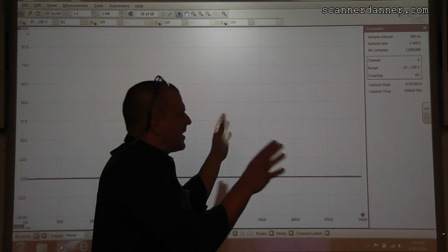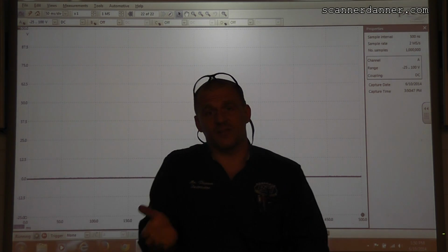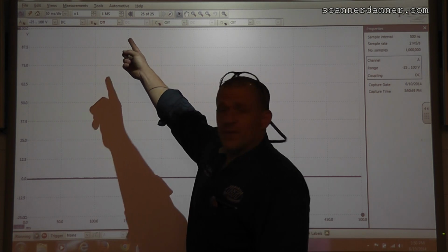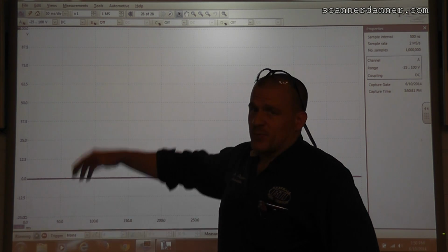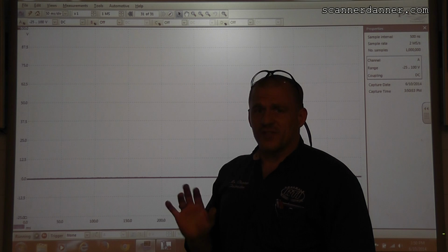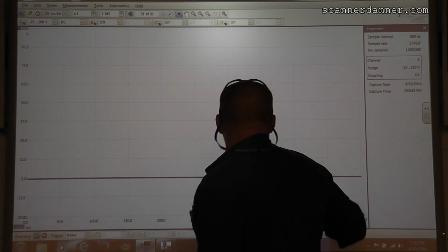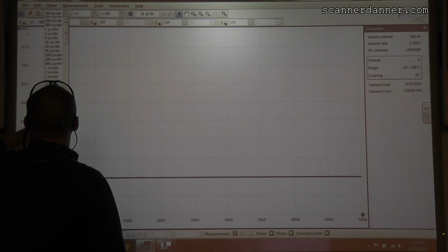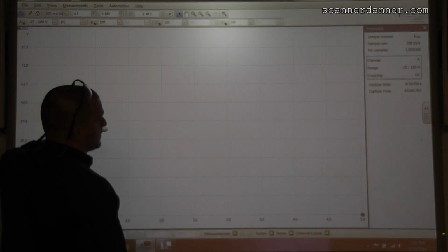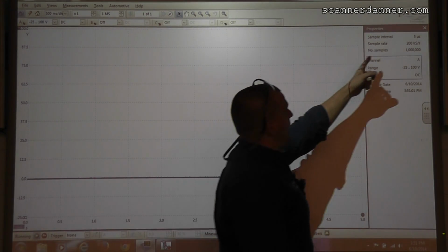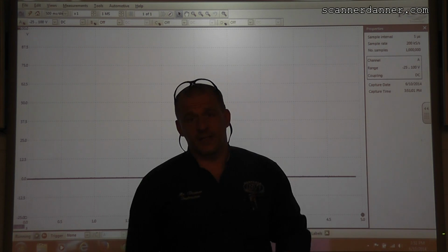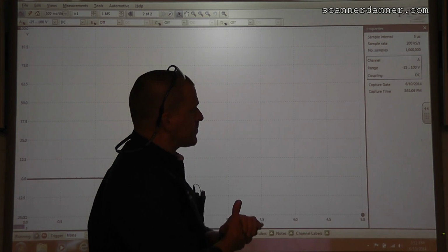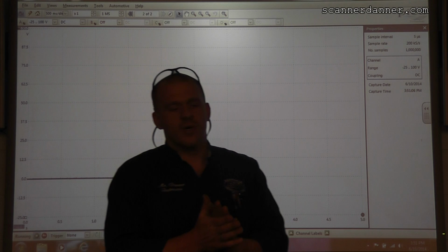I know you're thinking nanoseconds, that's really fast. Well, it is, and that's why we default this on 1 million samples. We still have a great amount of sampling taking place even on this longer time base. Let's go even higher. Let's go 500 milliseconds. And now I'm at 5 microseconds per division. So here's what we just learned.